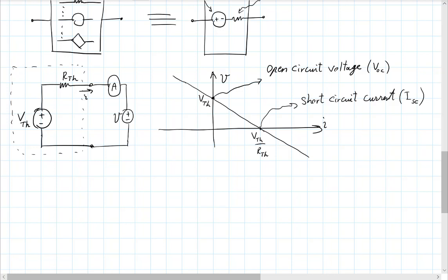Now, when you connect a voltmeter somewhere, you have still left it open, right? Because a voltmeter does not draw any current. An ideal voltmeter, of course, is approximate. But it just tells you what the voltage there is without drawing any current, without imposing any load. So a voltmeter connected there will just give you the open circuit voltage. And you know immediately that that's your Thevenin voltage. How would you do it on paper? Well, you would just leave the circuit alone.